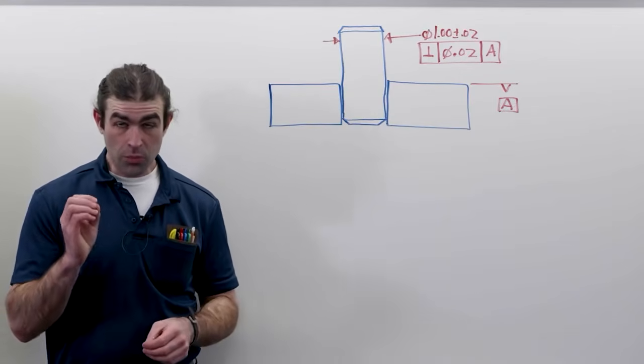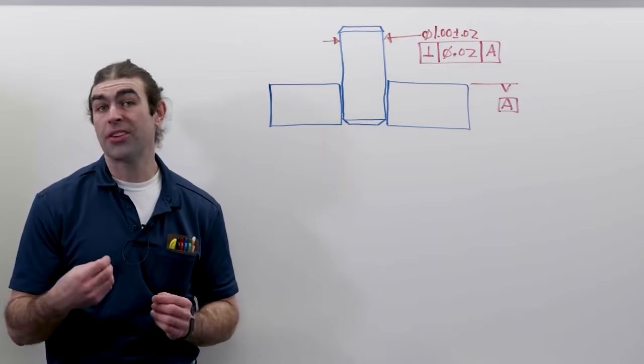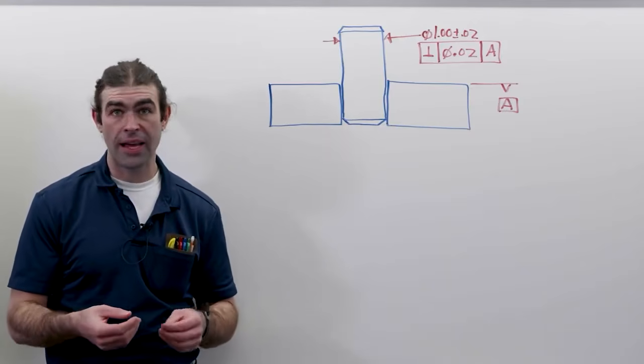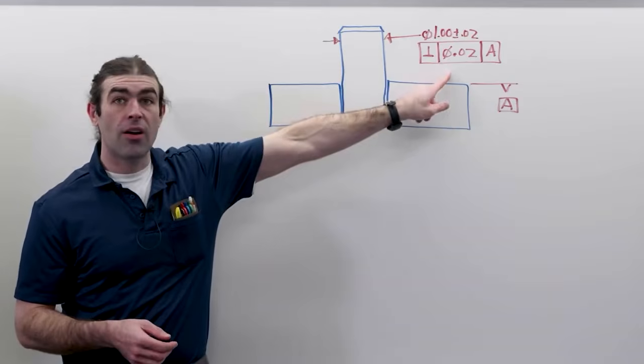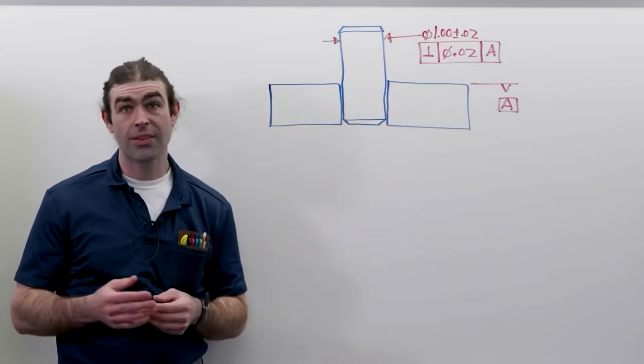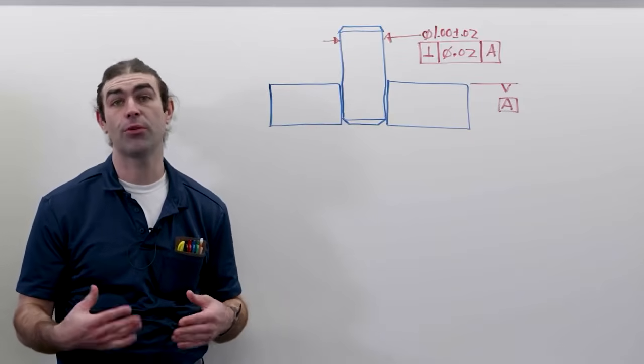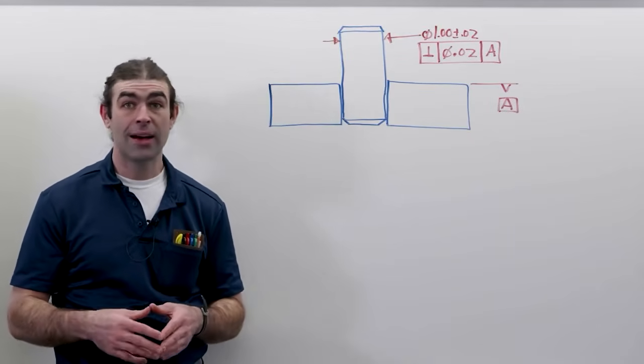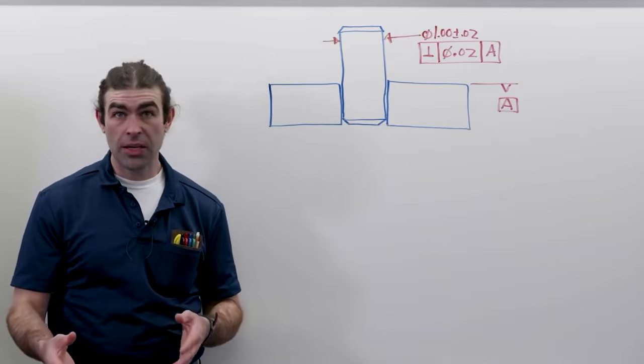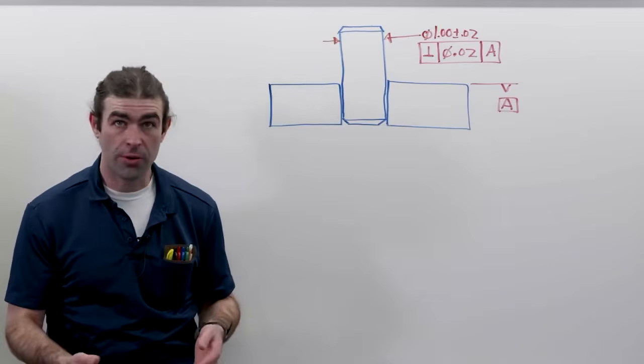Now, when this is applied to a feature of size, material conditions do apply. So this is applied at RFS, which just means that that tolerance of 20 thousandths applies no matter what size the actual feature comes in at. Now, if we apply it at MMC, we'll get a very different result. Let's take a look.